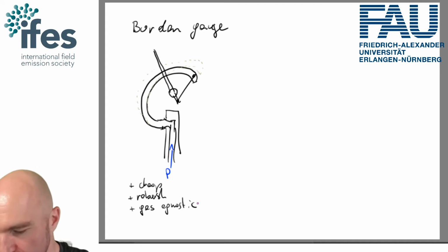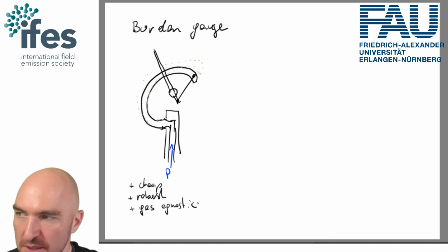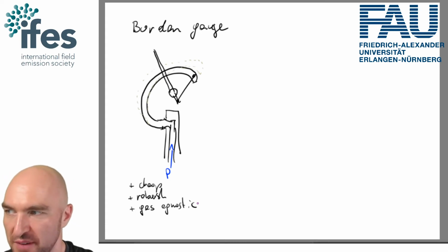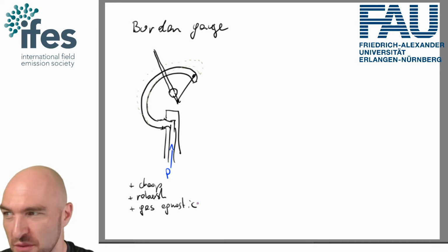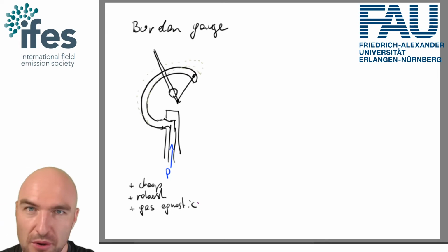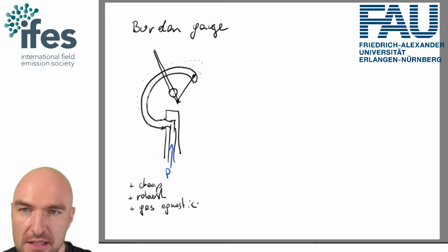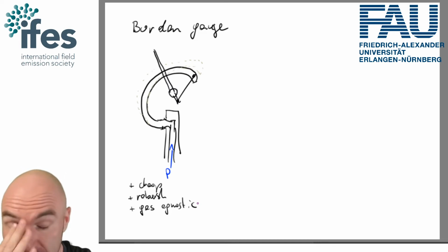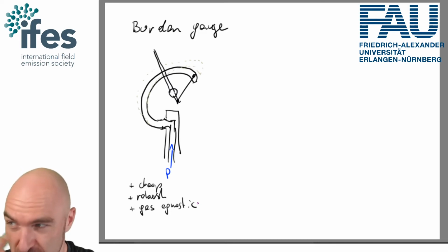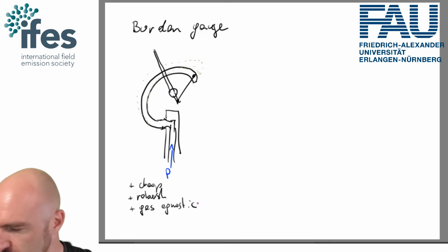But with the mechanical principle, force is pressure times area, and we are going through pressure logarithmically. So most of the force is gone once you're at a millibar. At a millibar, that's already 1/1000th of the pressure of ambient conditions, so measuring the force becomes pretty difficult.